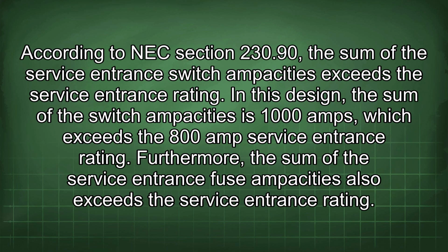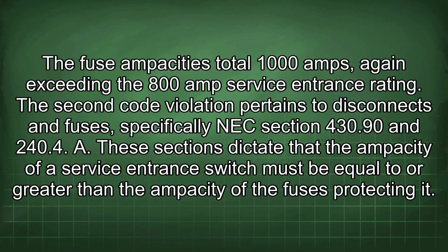According to NEC section 230.90, the sum of the service entrance switch ampacities exceeds the service entrance rating. In this design, the sum of the switch ampacities is 1000 amps, which exceeds the 800 amp service entrance rating. Furthermore, the sum of the service entrance fuse ampacities also exceeds the service entrance rating. The fuse ampacities total 1000 amps, again exceeding the 800 amp service entrance rating.